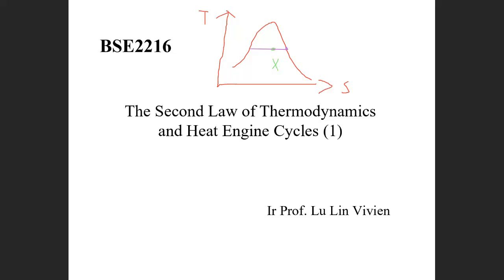From the saturated tables, we can find the enthalpy of saturated vapor and saturated liquid, then compare with them. So we know if a state is in the wet region or if it's superheated.